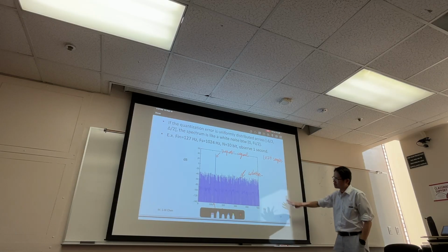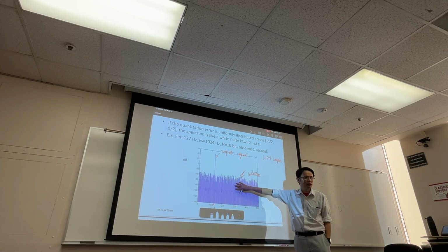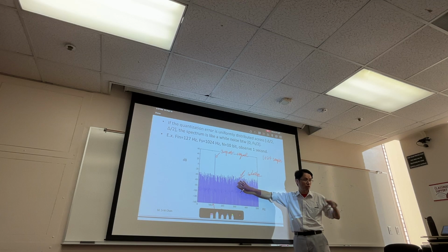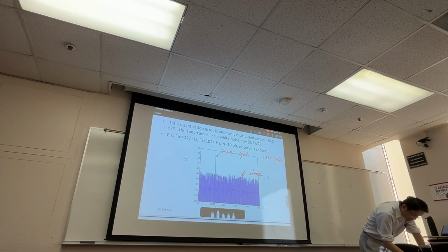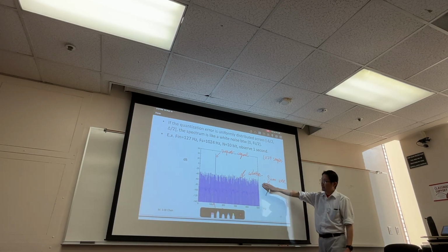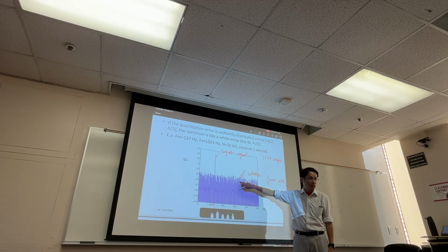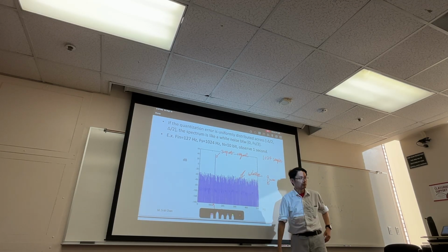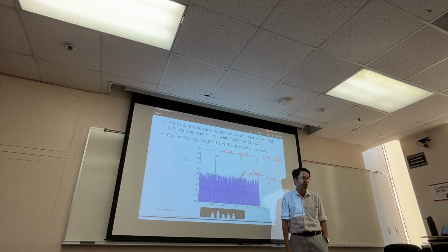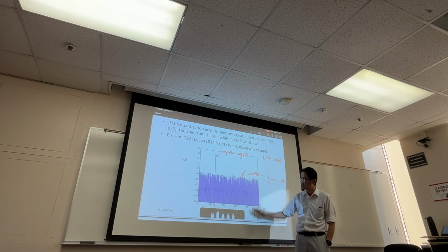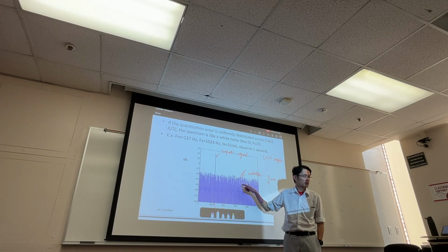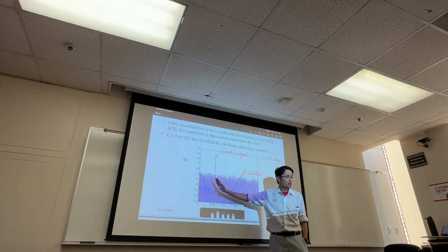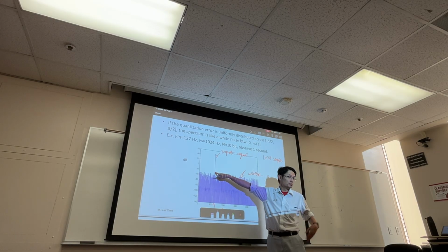Okay, so I see all those tones right here, and you said that correctly. This is quantization noise. If I sum up all these spikes' power, so I do a square sum, what do I get? You see a lot of spikes, right? In total it's 1024 spikes, and one is the signal.